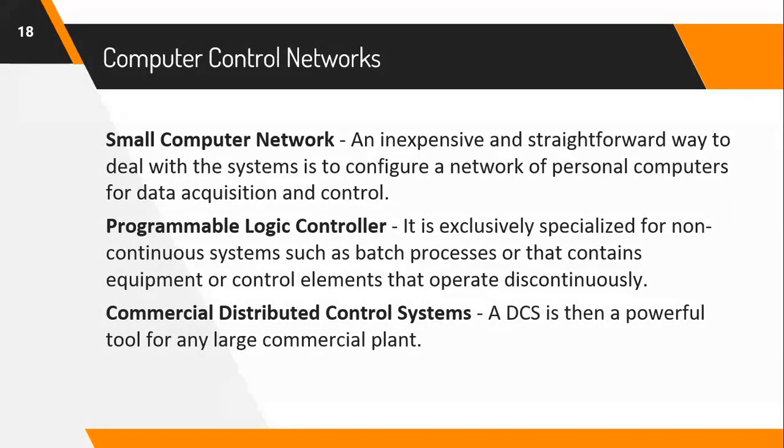So we can access a large amount of current information from the data highway of a commercial distributed control system. It sees the trends of past process conditions by calling archival data storage, alternates quickly among standard control strategies, and readjusts controller parameters in software. So a site engineer can use the flexibility of the framework to implement his latest controller design ideas on the host computer or on the main control computer. It is readily installed on a new line, measurements together with local computers for data acquisition, and then uses the new data immediately for controlling all loops of the process.